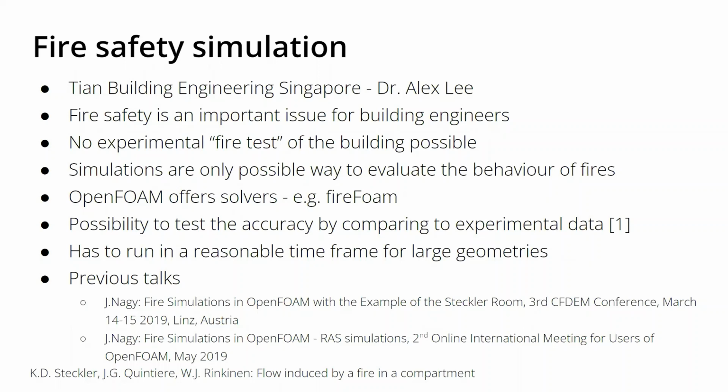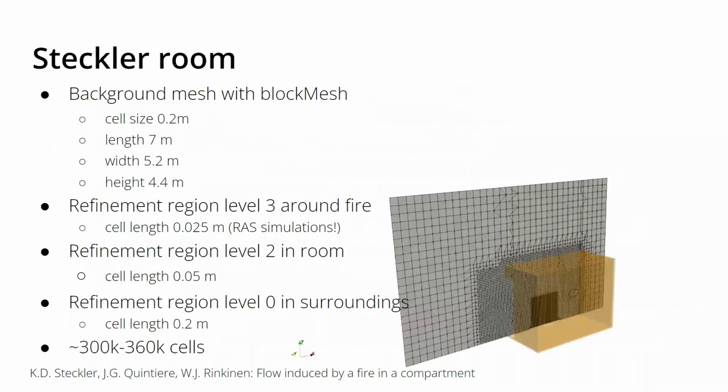And the thing is that because it's an engineering task and not an academic task, the simulation has to be run within a reasonable time of a couple of hours, overnight or maybe over the weekend, but you cannot run simulations for months in this regard. They also gave talks about that, so maybe you already know these results. But in the first step, we verified the possibilities in OpenFOAM with a verification and validation case coming from Mr. Steckler from, I believe, the 70s, where he built a small room.